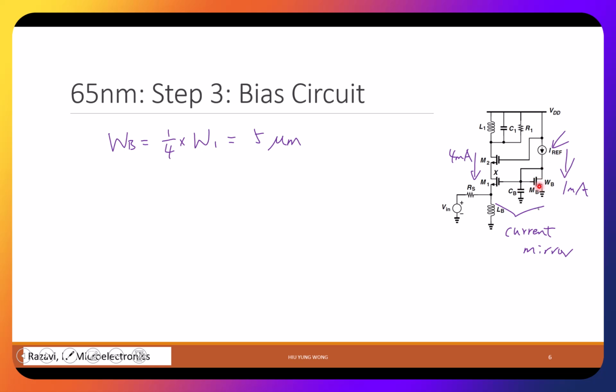So that is okay. If I were you, I think it will get too large, so you will just reduce the width of WB a little bit. It's not a big deal, right? Instead of 5, you just keep changing it so that this one is 4, right? Or if you really want, how about just making the current source smaller, right? No one mandates that it needs to be 1 milliampere. The goal is whatever comes out of your calculation. Now, you might not get 4 milliampere.